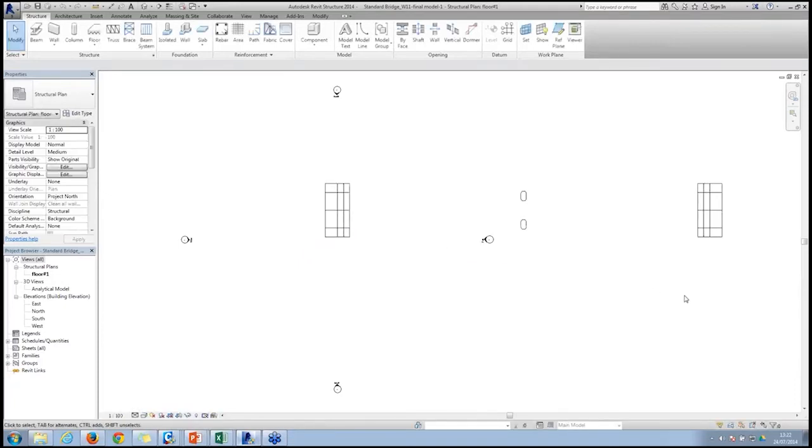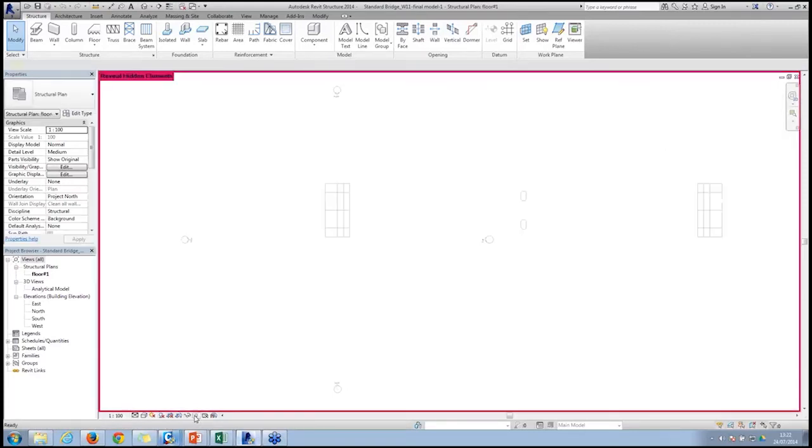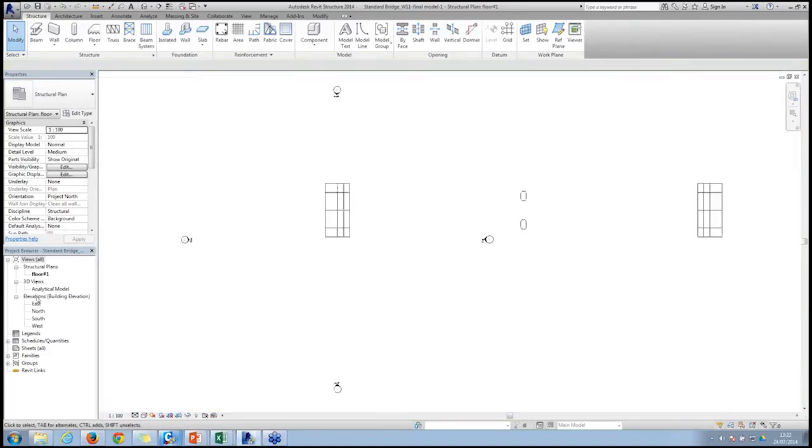So normally for glass, we'll go for orthotropic material, and we use plate elements for the deck, so not composite sections. What we used, a grillage model in today's example, but instead of a grillage model, we model the plate slab as plate elements for such type of user-defined sections.